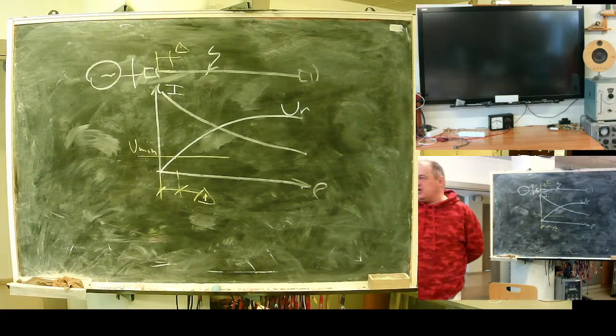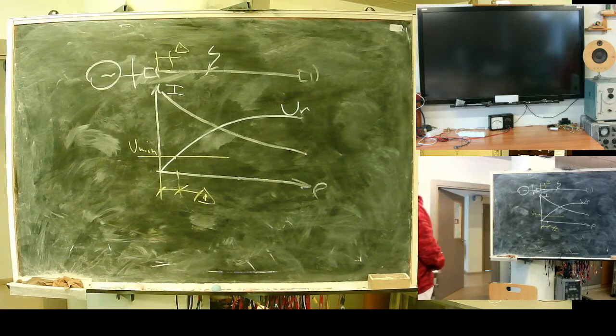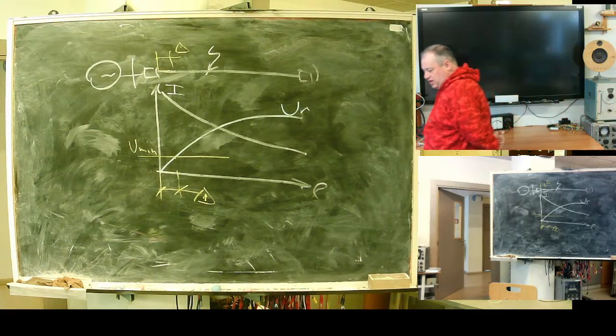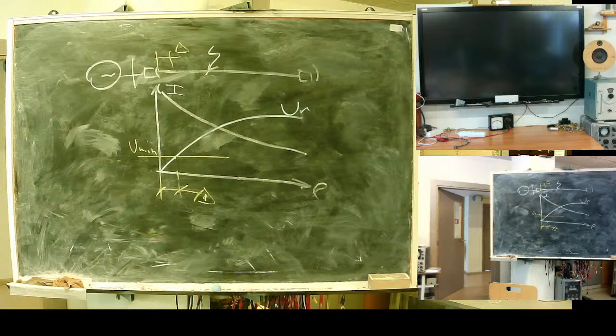second generation relays were equipped with memory circuit, resonant contour powered from third phase. For example, if we have AB voltage relay operating with current IA minus IB, C phase was used to power this resonant circuit.